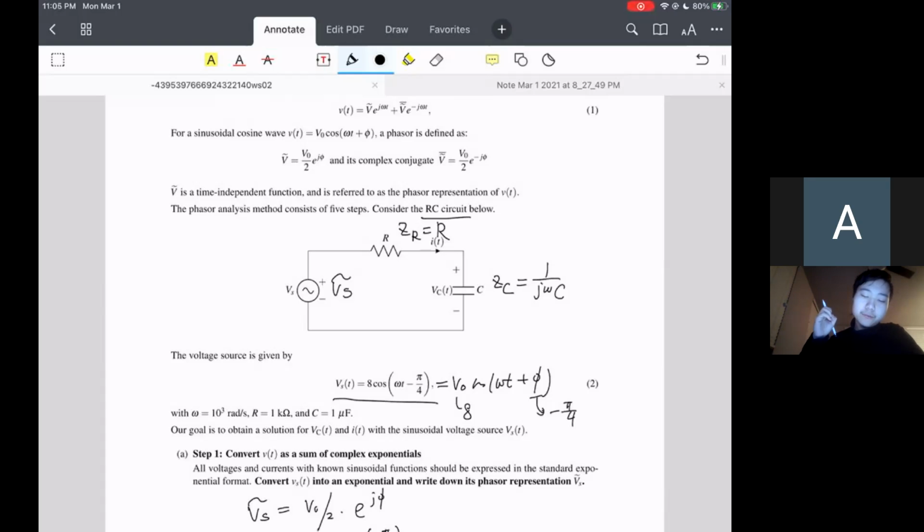And we also have the phasor versions of KCL and KVL, which means we can just treat all these components as resistors. Although the resistance might be a little bit weird, with complex numbers as in the case of the capacitor, we can still treat them as resistors within the phasor circuit.